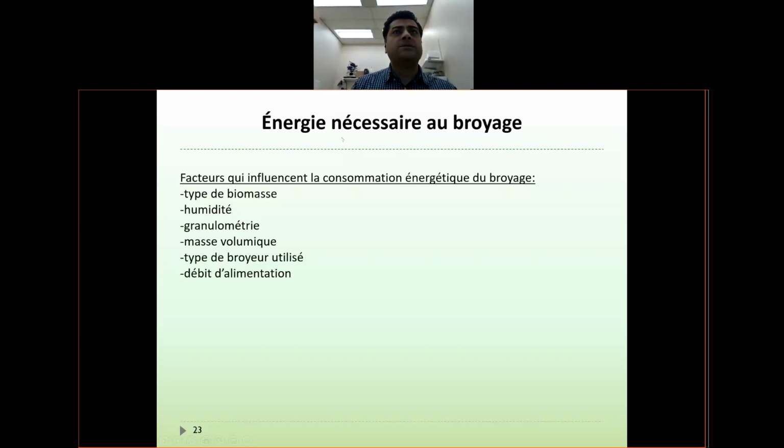So as you watched in the video, one sort of dryer is the rotating dryer. It's a rotating drum, as you can also see in this picture. And heating can be direct or indirect. I showed you that picture of how indirect looks, with those two bundles.